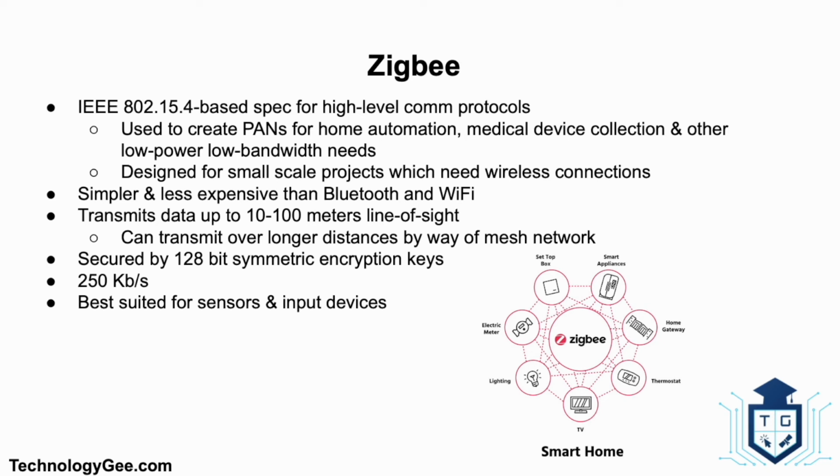The technology defined by the Zigbee specification is intended to be simpler and less expensive than other wireless PANs, such as Bluetooth, or more general wireless networking, such as Wi-Fi. Applications include wireless light switches, home energy monitors, traffic management systems, and other consumer and industrial equipment that requires short-range, low-rate wireless data transfers. Its low power consumption limits transmission distances to 10 to 100 meters, line of sight, depending on power output and environmental characteristics, and Zigbee devices can transmit data over long distances by passing data through a mesh network of intermediate devices to reach more distant ones.